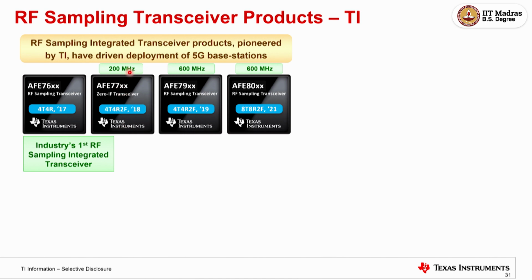The second architecture that I mentioned is the zero IF architecture, which removes the bulky filter. The first architecture we discussed, the legacy architecture, was just to introduce, and that typically is still there, but it is all on your macro, like GSM, not 5G; the 3G and 4G still use that. That's the majority of the market, because there is so much effort and money, financial implications, to change all the base stations.